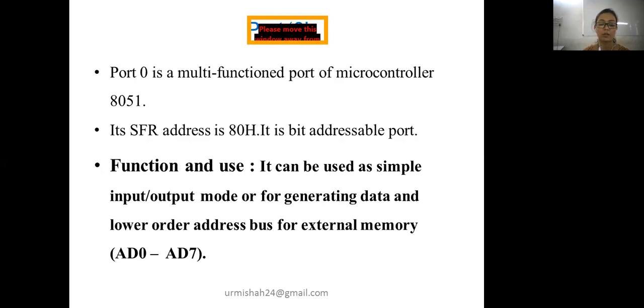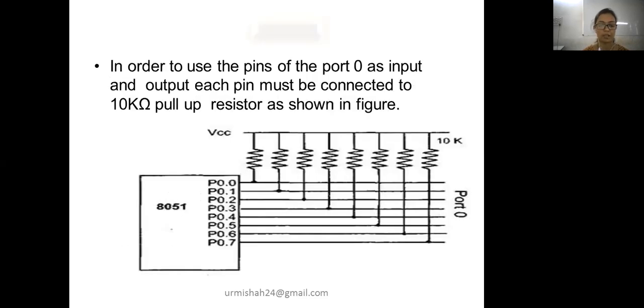And the lower order address bus includes the AD0 to AD7 pins of the microcontroller. Now whether you want to treat the 8 pins of port 0 as input or output depends on the connection you are giving. In order to use these pins of port 0 as input and output, you have to connect them with a pull-up resistor.